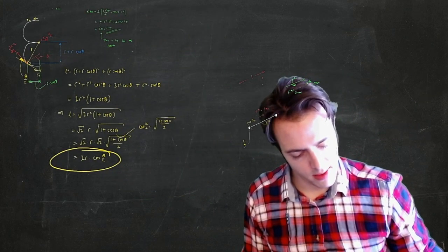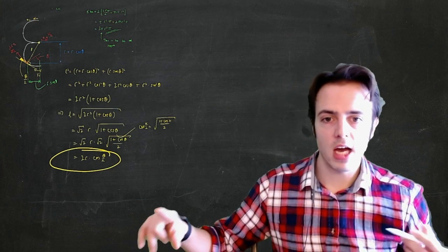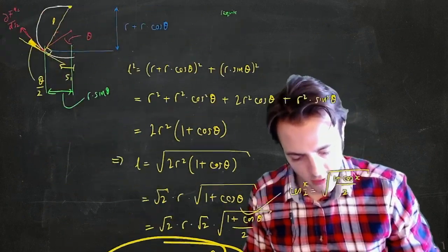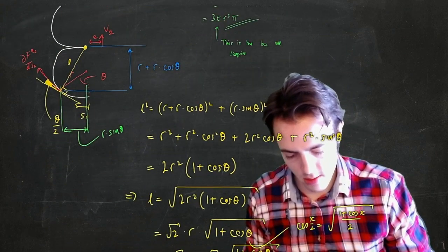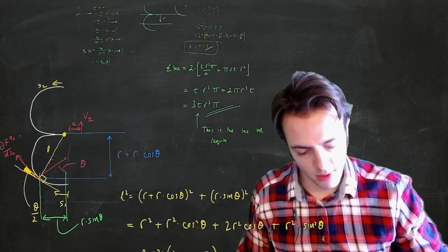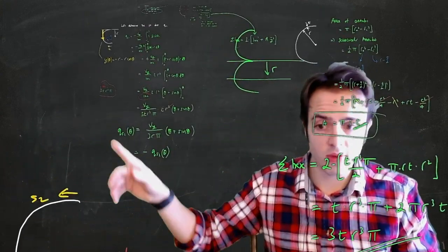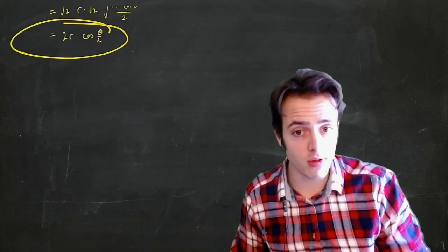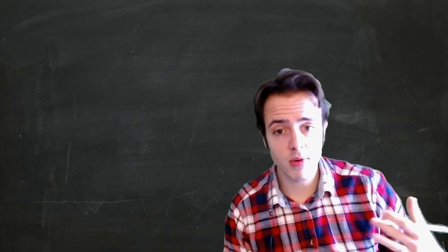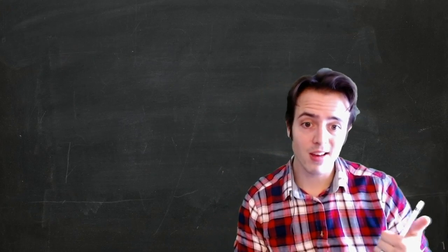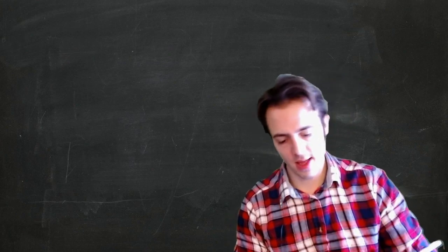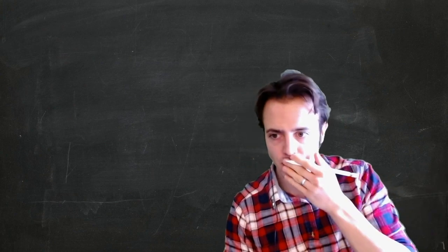Let's erase this bit. So what we've got now, we've got the moment arm, which is this bit here. We've got the part of the force that we need, so it's going to be cosine theta on 2, and we've got the shear flow distribution, which is up here. So we've got everything we need to determine this, but they're all functions of theta at this point, which we haven't got yet. So unlike previously, the angle is a function of theta, and also the moment arm is as well. So these all need to go into this function, so into the integration.